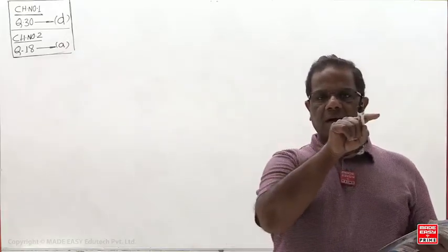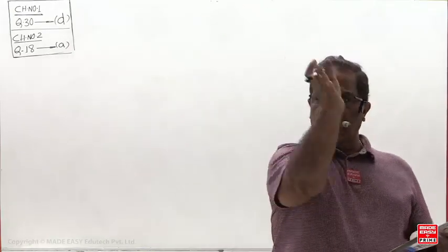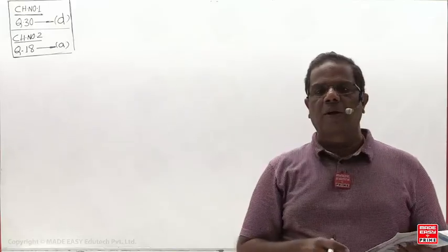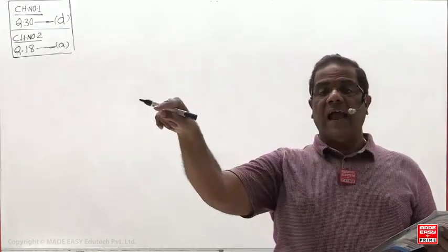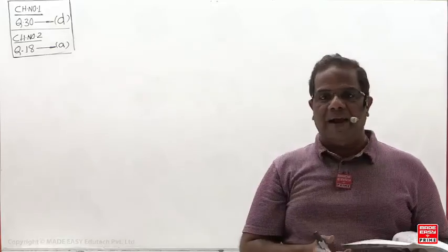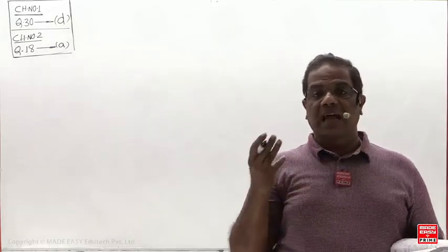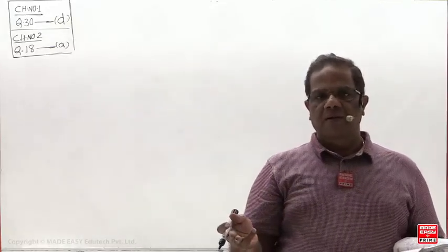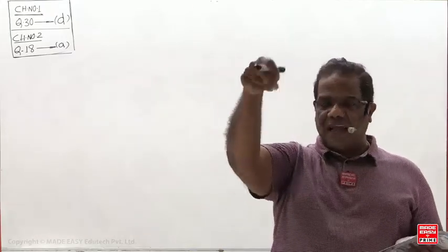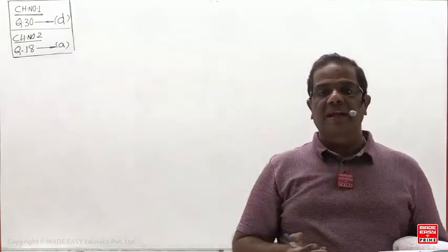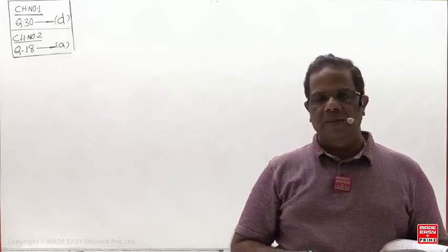Yesterday I taught: what is the angle between the oblique plane and the line of action of the load? What is the angle between the line of action of the axial load and the oblique plane? It is 90 minus theta. So when theta is 45 degrees, mild steel's fracture will be at 45 degrees, which you measure from the cross section, so theta is 45. Then 90 minus theta is also 45.